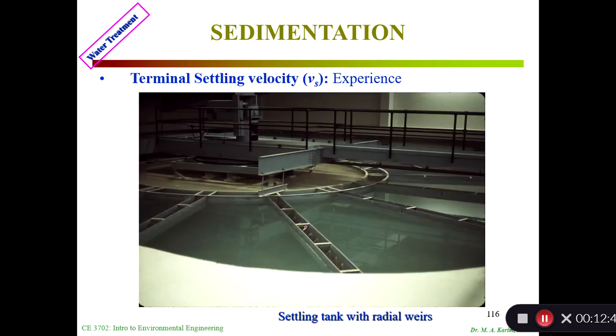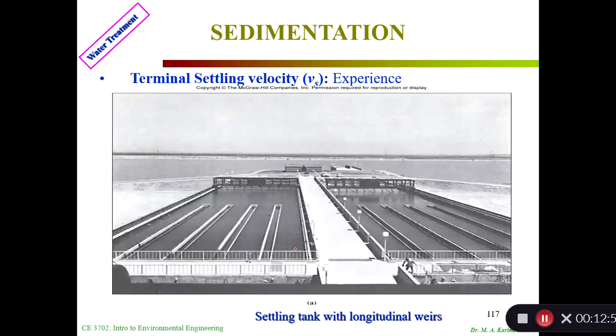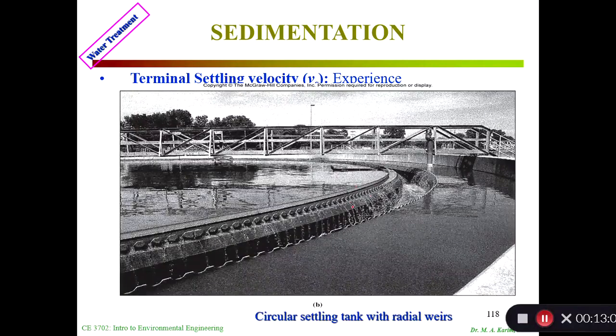So this is the settling tank with radial weirs. So these are the weirs I was talking about, right? They are saying that once the water goes above this, then it comes here. This is a flat weir, a simple weir. This is not a V-notch or anything like that. I think I may have some V-notch. I think these are V-notch, right? Okay, yeah, this is definitely V-notch. I don't know if it's 90 degree or 45 degree, but it looks like these are the V-notch weirs. The problem we solved came out to 288 meters, so it could be a total length of 288 meters.